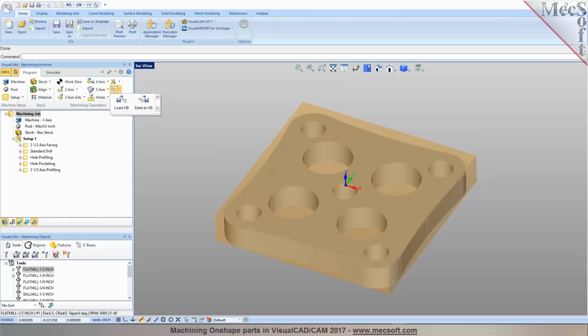Okay. So this is a very nice feature which helps you, the programmer, be more productive and reduces the amount of time you spend going back and repeating the same workflow over and over again. Okay. I think I understand it perfectly: if it sees the hole diameter, if we were working in metric, say 10.25, it would know it was a hole for a 12 millimeter tap.